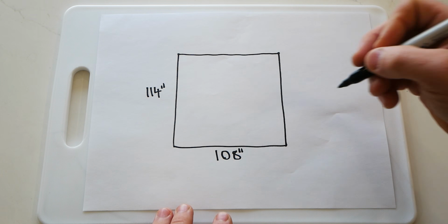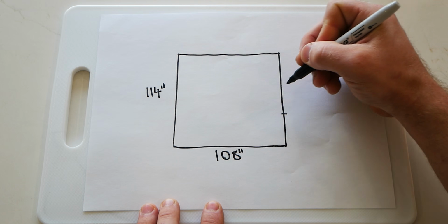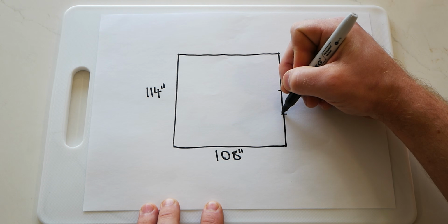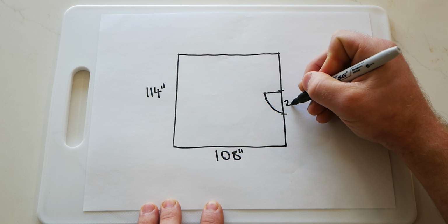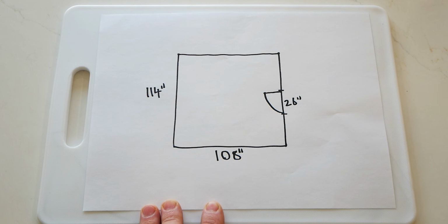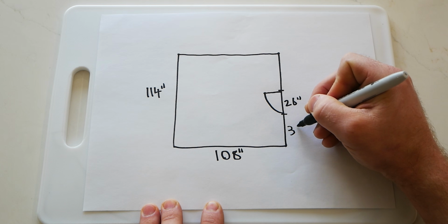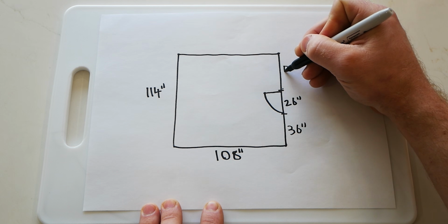And then once I have my two walls kind of figured out, I can then go ahead and start adding in some more details. Next, I'll add the entry door, as that's most likely going to stay where it is. And even if it isn't, it's nice to have an idea of what we're dealing with. So I'll put that down. I'll record the swing of the door as well and sort of the size of it. From there, I'll figure out the distance from that edge of the door to the corner and then do the same on the other side.